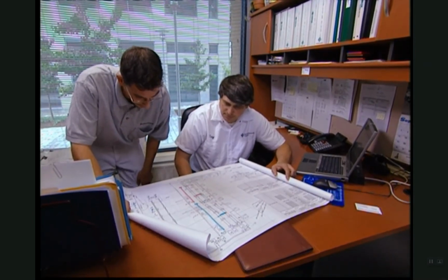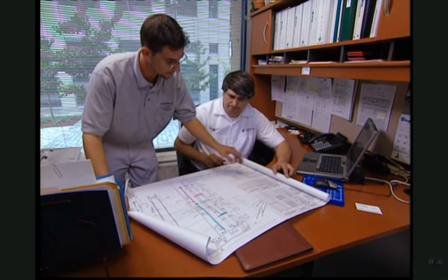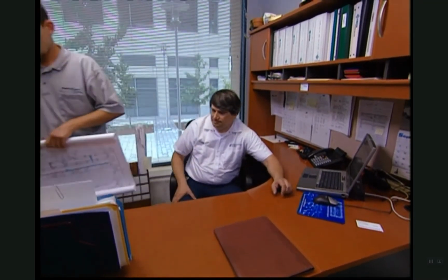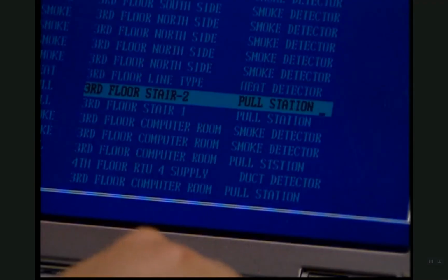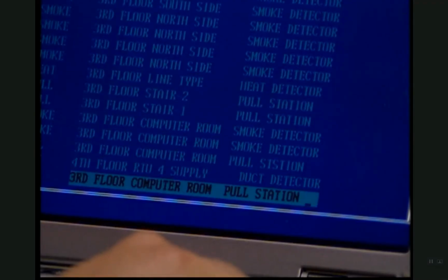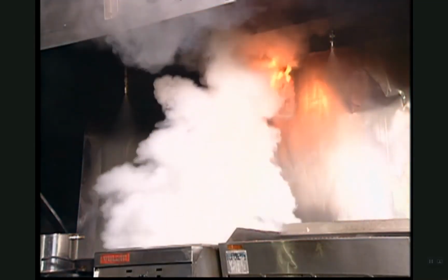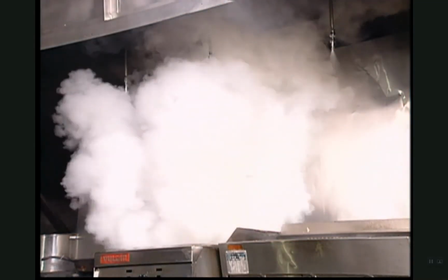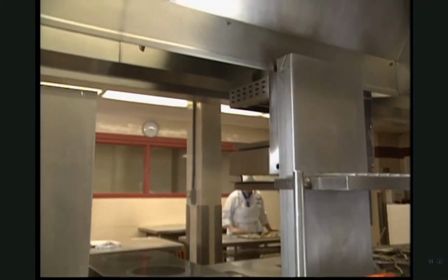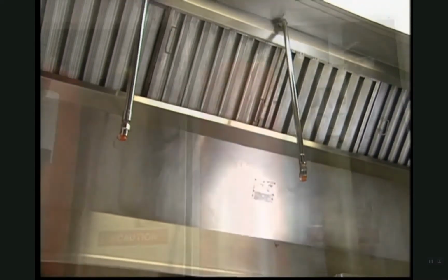This underlines the necessity of good record keeping, so that you test every device at the correct interval, and you maintain accurate and complete information for each test. Test extinguishing system alarms only if you are qualified and experienced with these systems, and only if you know how to prevent inadvertent system discharge.